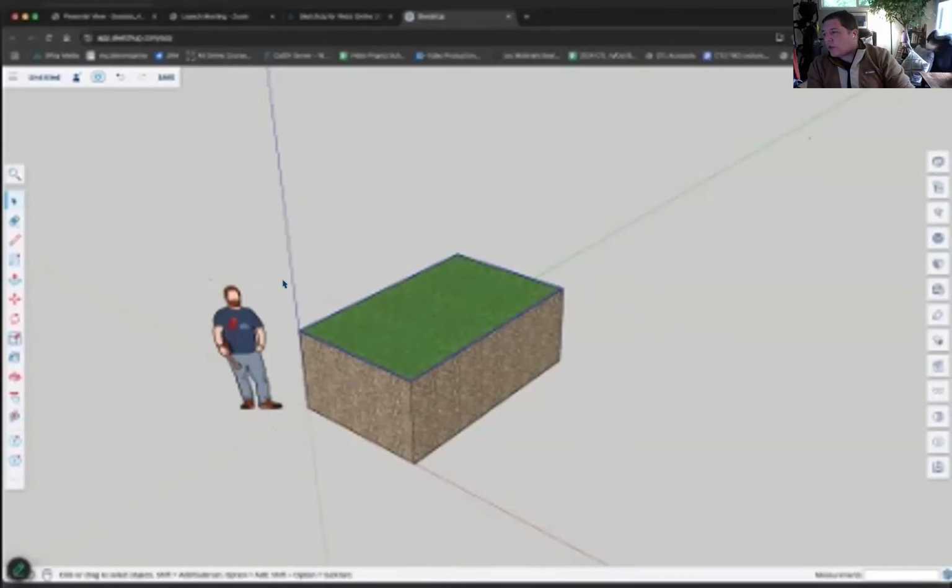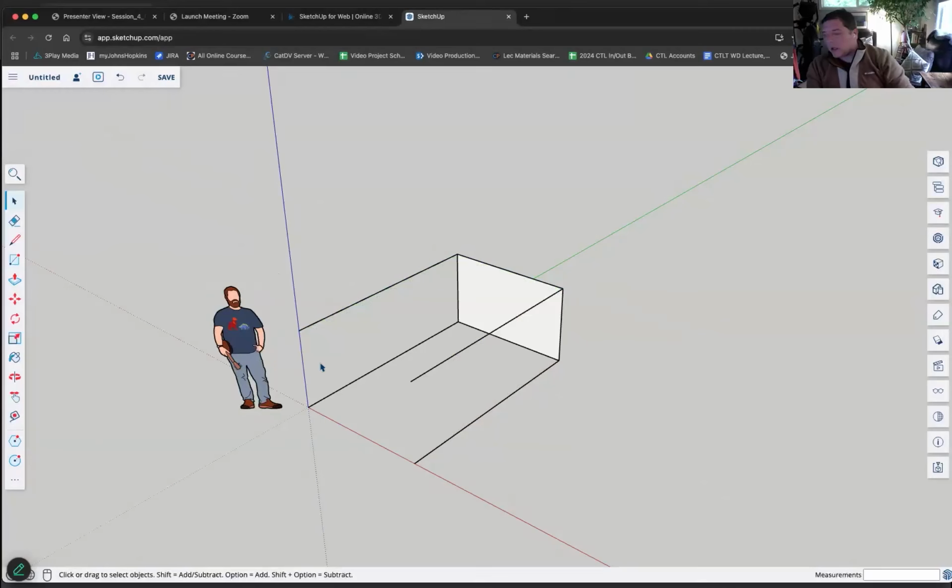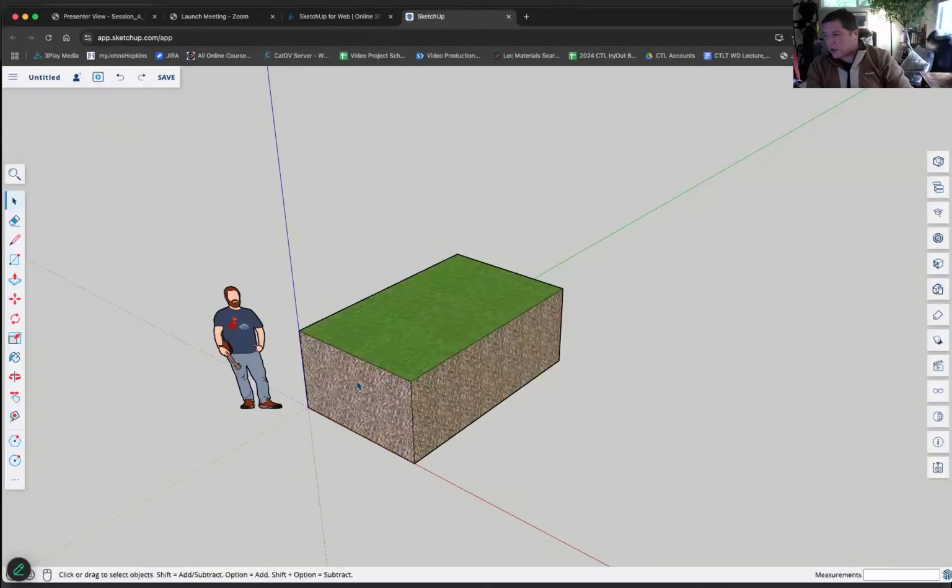One thing you can also do is, let's say you just want to edit just this side of it here. I can click once and then double click, and you see how a blue frame came around that. If I hit delete, oops, didn't mean to do that. Should be able to delete just that side. There it is. So all I did there was I just hit select once and then I hit delete, and that allows me to open up that shape and work with it again. I can also just do that to create an open box.